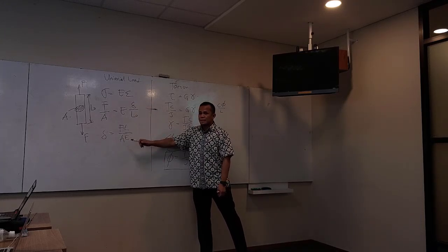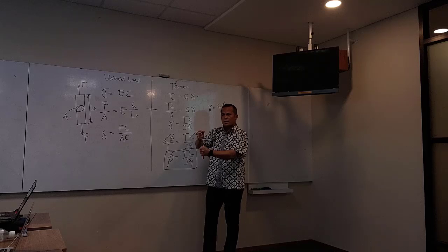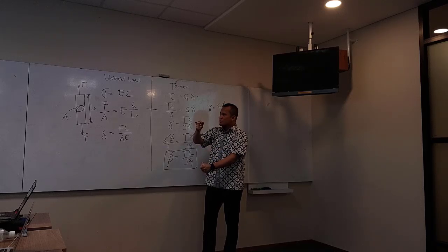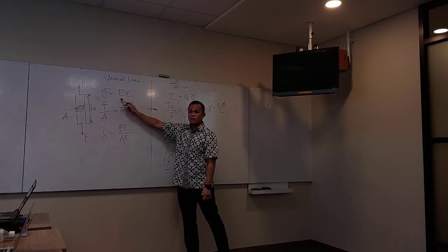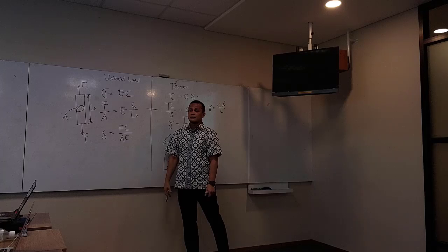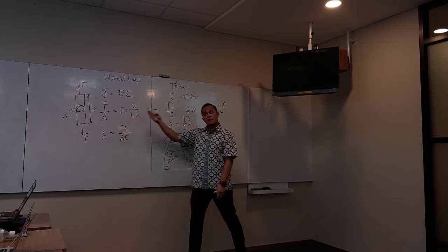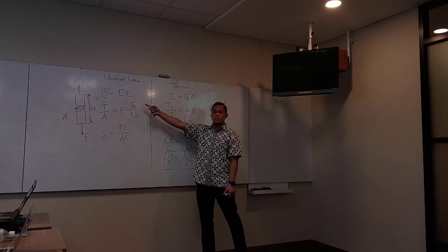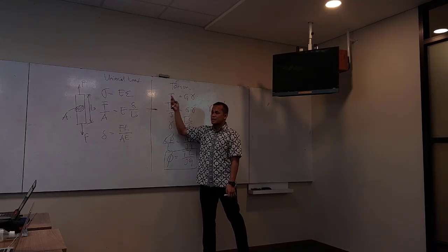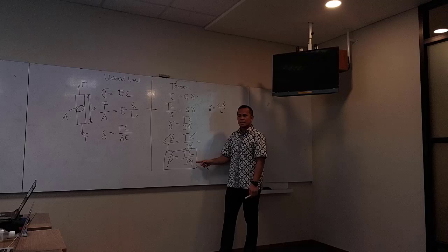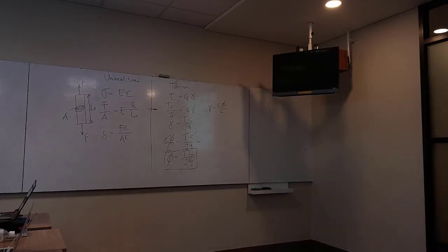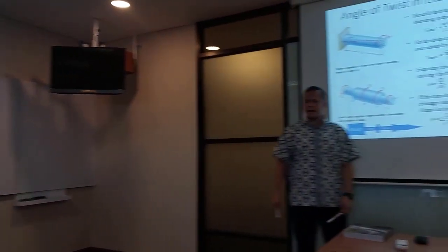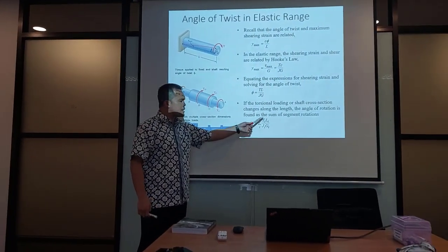In this uniaxial case, because the loading mode is uniaxial, it corresponds to Young's modulus, because Young's modulus is often from tension, tensile. But because now the load is torsion, E is no longer applicable. It is under shearing, so shear is G. Is it right? Okay, good. So that's how you remember the relationship between twisting angle and the shaft parameter.